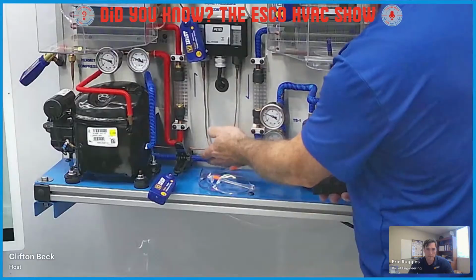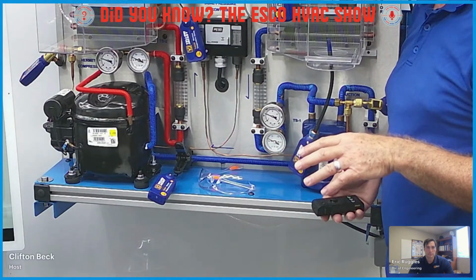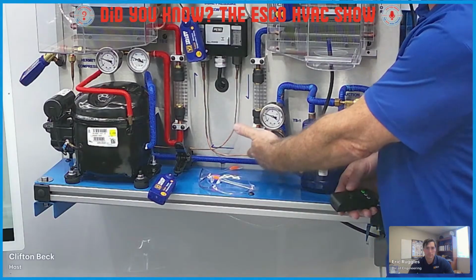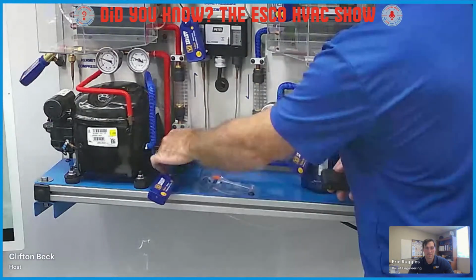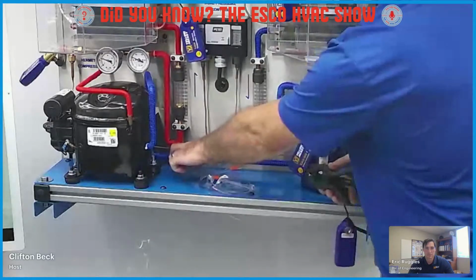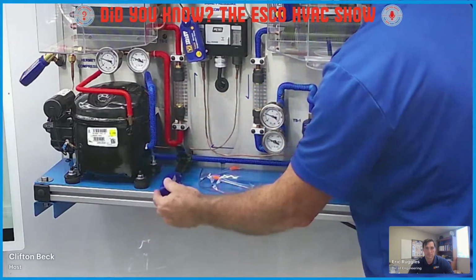Right. So I went ahead and labeled this entire unit. And for instructors, this is a really inexpensive thing for you to do in your classroom on any of your trainers. Simple blue electrical wire loom and red wire loom so that I can mark the low side and the high side of the system. And then I left a section exposed so that I have my bare copper to be able to attach my clamp onto properly. So this particular one is on my low side.